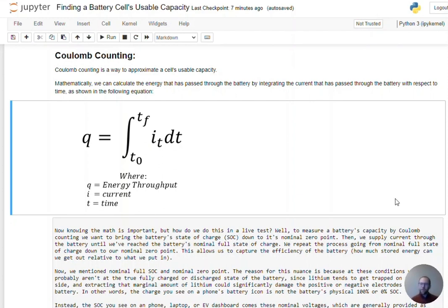And if we were starting the battery at its minimum operating condition, where it's around 0% state of charge, and ran it all the way with a supplied current until it hit its maximum voltage operating condition, or 100% state of charge, and we continue to apply some supplemental current, maybe tapering it to make sure that we are maintaining a voltage, that can get us to our approximate 100% state of charge.